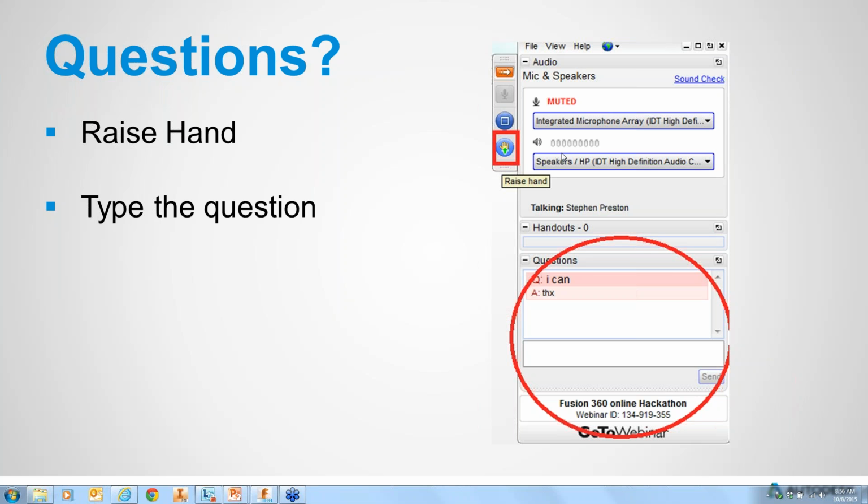Okay. And then the other question, the cone. Yeah, the cone, because it's not available in the solids. It's just like a cube, but you have a cone in surface geometry. So can you actually create the cone through the API? Well, none of the geometry, like I said, can you explicitly create through the API. You create it through features, right? But you can't create cones through features. So if I just draw a circle and do an extrude, I can give a draft angle to that extrude, so that will create a cone.